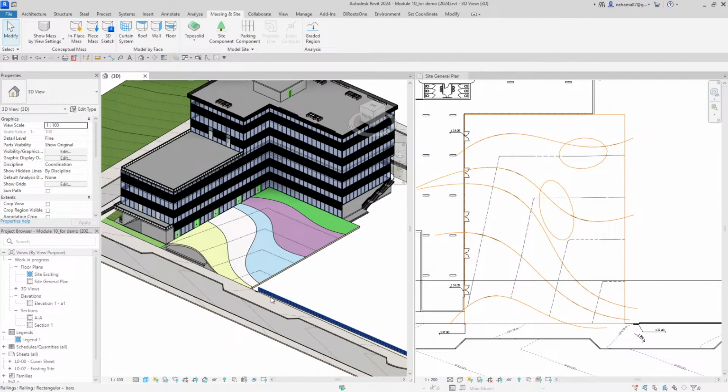I noticed that if I pick a level in the main properties, the Toposolid is still placed at sea level. I pick from edge, but when I hit finish, it moves down to sea level and I have to raise it. So the reason it still stays at sea level, it's supposed to change the attached level, but the elevation should stay the same.